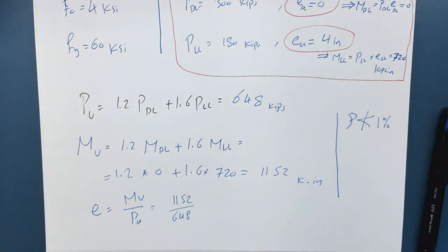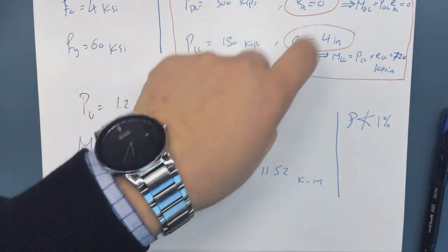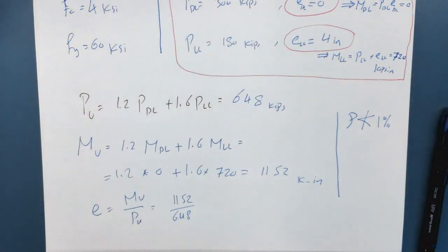You have to add 1%. So the area of steel in this case is simply 1% multiplied by the gross section, which is going to give you 3.2 square inches. Okay. So again, the two tricks in this problem. The major one is that each of those has different eccentricities. The other one is that it's inside the envelope, so use the smallest envelope. Any questions about those?